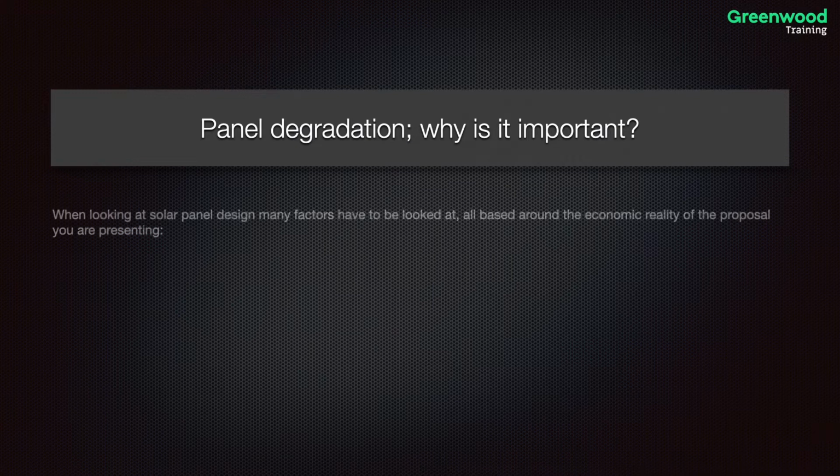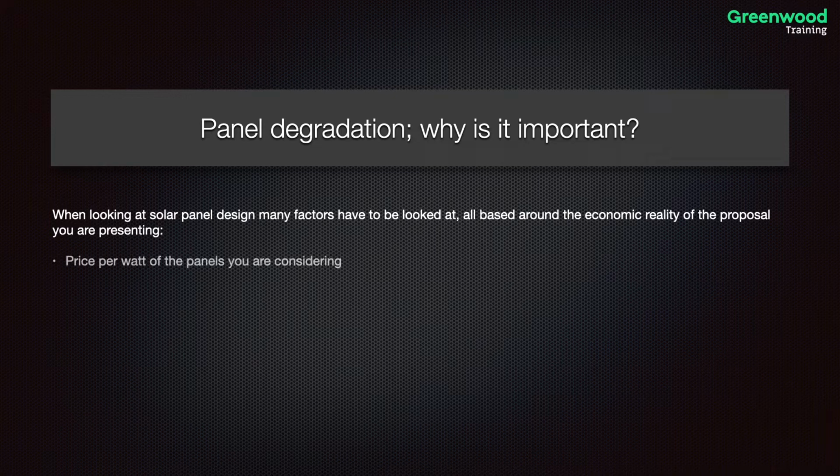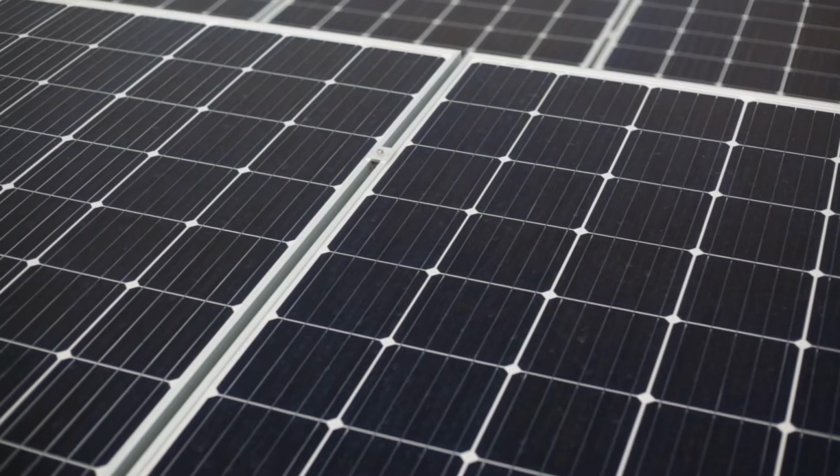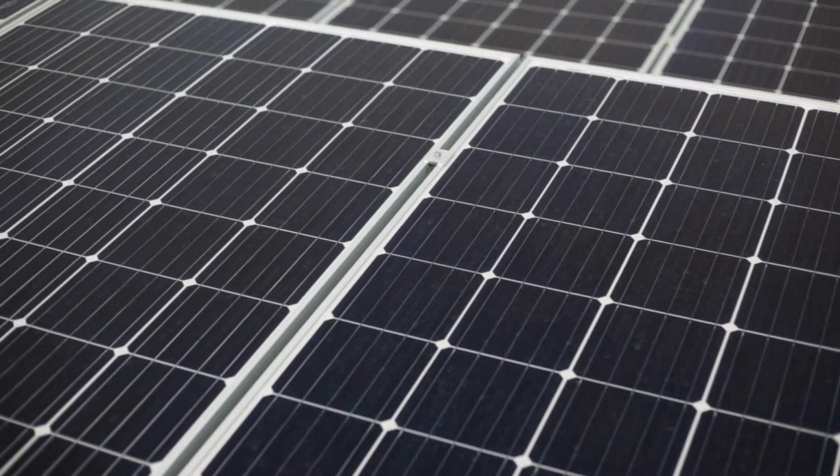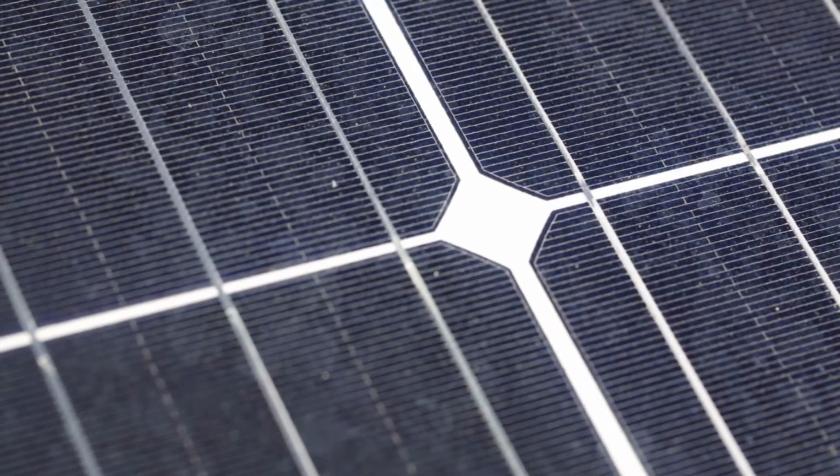So when looking at solar panel design, many factors have to be looked at based around the economic reality of the proposal you are presenting to the customer. So the price per watt of the panels you are considering, the overall efficiency, and this is really important if space is at a premium, the actual output over the lifetime of the panel, and we're going to look at 25 years, and this relates to the degradation.